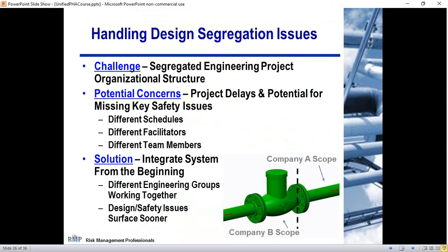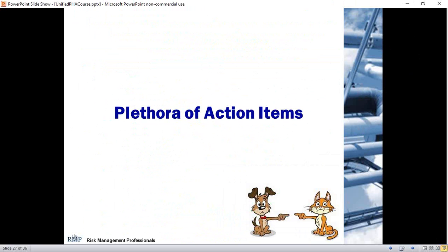And again, in all these cases, the sooner the better. A good facilitator can also deal with preliminary information. So you can do a fairly light effort, look at a lot of key scenarios early in the design. Then as the design matures, back to that design cycle that we looked at before, you can go ahead and infuse and update the HAZOP and LOPA if you've designed the HAZOP and LOPA for easy updates. All these things come together in terms of doing a good job with HAZOP and LOPA for a big design project. So it never goes well, or at least not 100%.